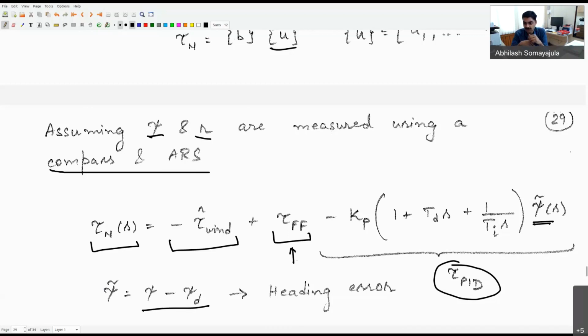So remember that in our original discussion when we started off this control systems, we talked about this idea of successive loop closure, right? So we can now talk about that, where now the heading is matching, but I want it to go through certain waypoints. Then I can try to change that guidance system slightly.